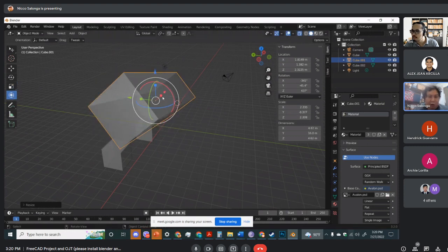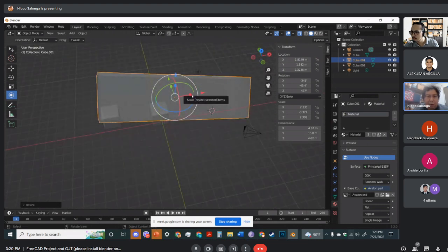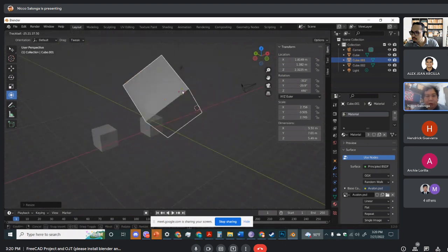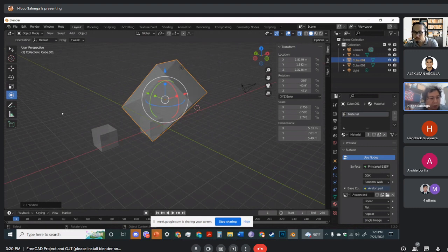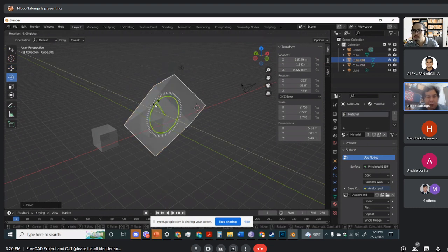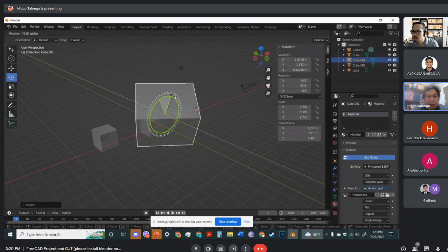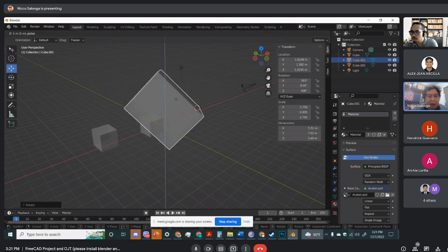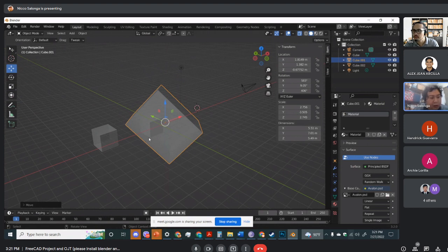Now this combines all the tools into this kind of convenient but slightly messy interface. It's useful for a lot of things when you're making objects and large numbers of them and positioning them. So another thing to note is that when you're using these and you press Control, it snaps it to a grid, or in the case of rotate, it snaps it to certain degrees. Not sure how many those are, probably like 5 or something. If you want to make sure that you always have proper angles divisible by, I think, 5 or 10 or something, or the proper distances and exact distances. Okay, so that's it for moving these around.